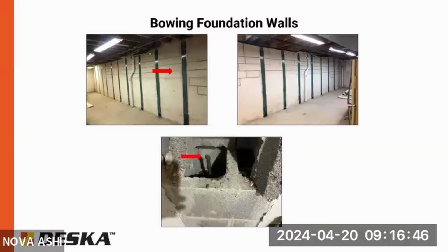Another potential way to deal with the shearing aspect is you can actually do what we call shear pinning, which is where you actually core the face of the wall, install steel reinforcement in the wall, and then grout it and fill it with concrete, essentially.